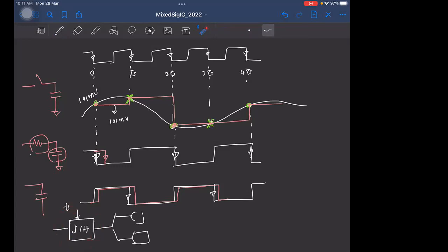In these cases, we resort to digital calibration where you have multiple phases of the clock and you use the appropriate phase to make sure that the timing skew is cancelled. But the question was, if you can interleave the ADCs like this, the original point was we are not able to operate the ADC at the full speed. So we took two different ADCs operating at half the speed and interleaved them, right? So the question was, why can't we do the same thing with the sample and hold also? That is, why don't I have the sample and hold also operating at the half rate?